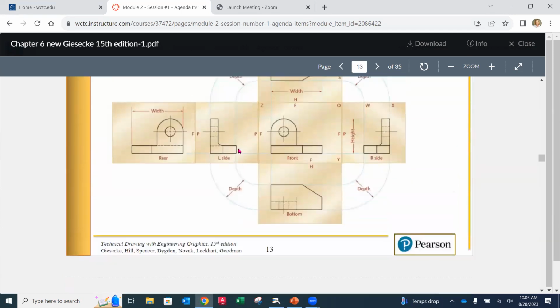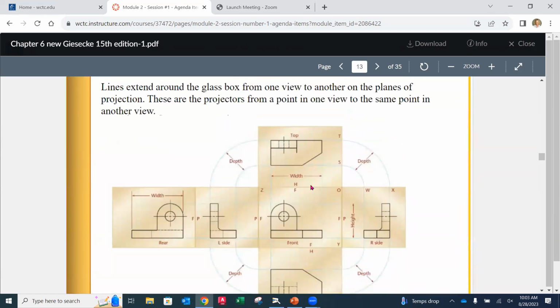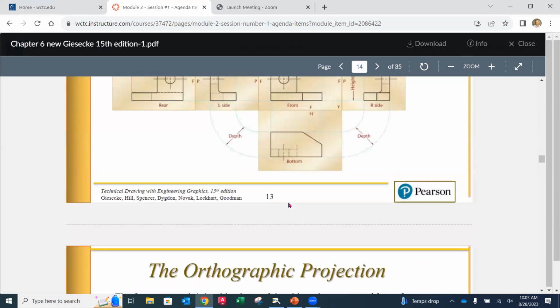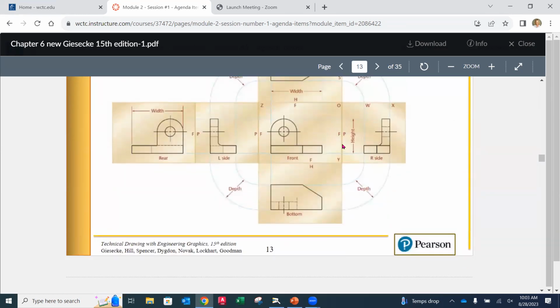So if I go back over here, that's going to be this dimension from the folding line back to where that view starts. Okay. And so on. And then we would do that same thing, folding line between the top and the right side. And that's this folding line here. And then it tells us, oh, how far back is that point going to be into our view? Okay.